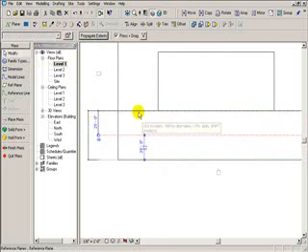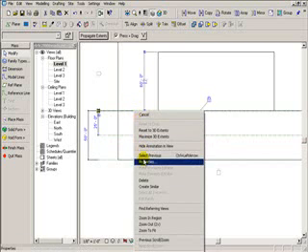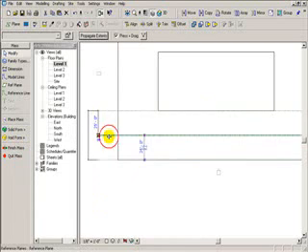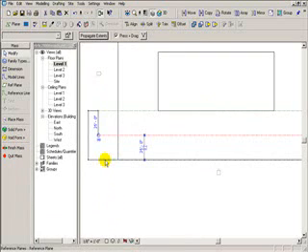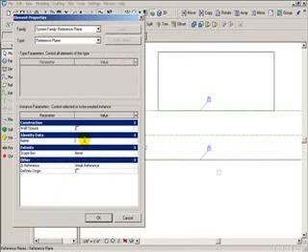I'm then going to name these reference planes so that they do become work planes. Because this is the interior and it's south, call that interior south. Call this middle one mid south, and I'll call this exterior one exterior south.